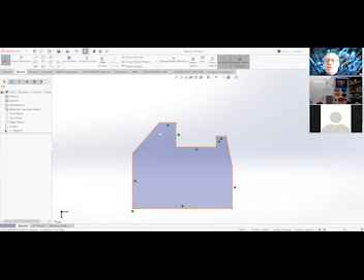And as we go, we'll add some of those. Like you can make sure that the corner is always 90 degrees by forcing it to be perpendicular. We can force lines to always be parallel. And we'll then do quite a bit of that with the next few drawings we do. We're going to be spending quite a bit of time here for the next few days using SolidWorks.